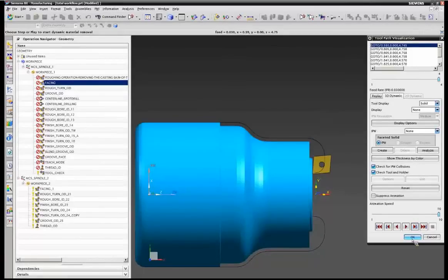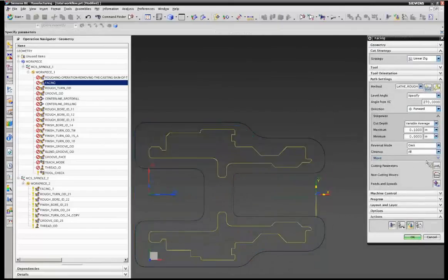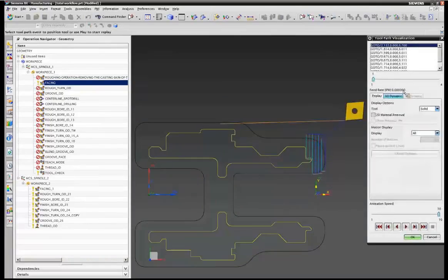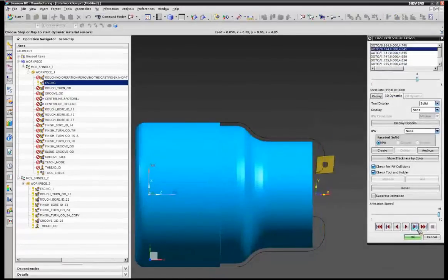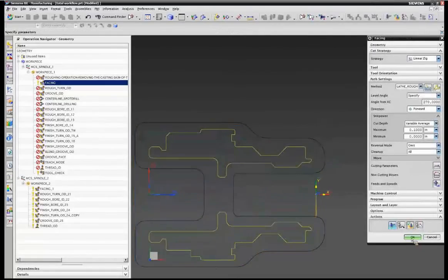This is something you don't want to have. So the system has been updated so that we now remove all those recuttings in roughing. Whenever you regenerate those operations, you will notice that the same pass will go and cut the original level and then will retract once it reaches the same area.